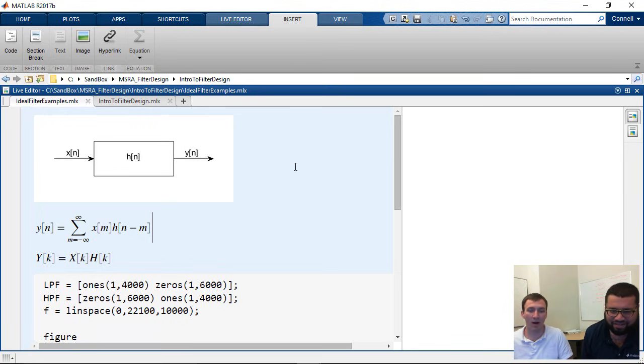Common practice in signal processing is to convert everything into the frequency domain, and what this does is this converts the convolution process into multiplication, which is much simpler. So just to stop at how do you convert a signal from the time domain to the frequency domain? To convert a signal to the frequency domain, we use the Fourier transform. And in the software demonstration, I'll talk a little bit about the tools that MATLAB and MathWorks products provide to support this workflow. Cool. Okay.